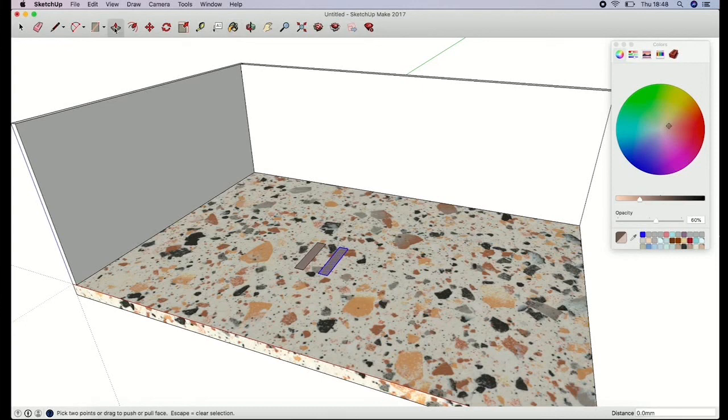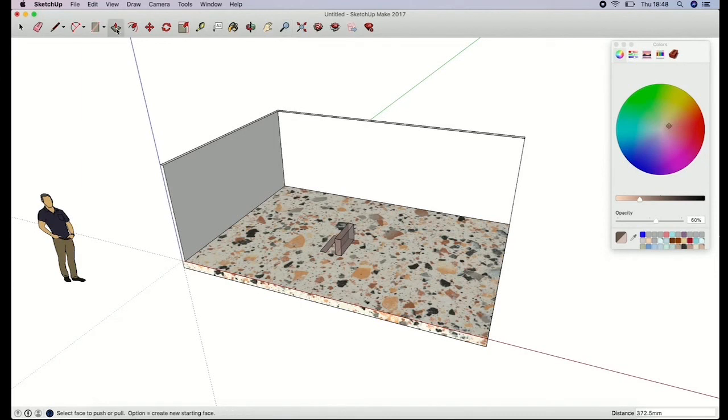And also using Extrude, I can click on this tool and drag that surface up, and maybe to see how far I want it. And if you click on a surface that you want it to be parallel with, so this will go to the same endpoint or to the surface parallel to the other leg, you can also do that.